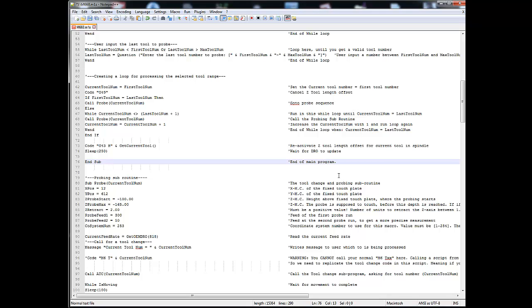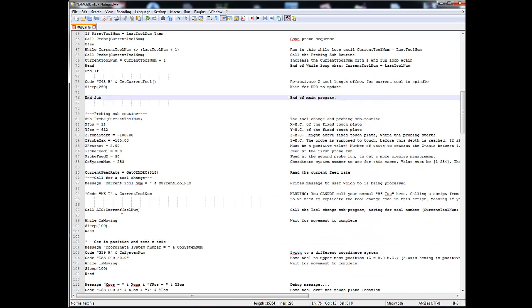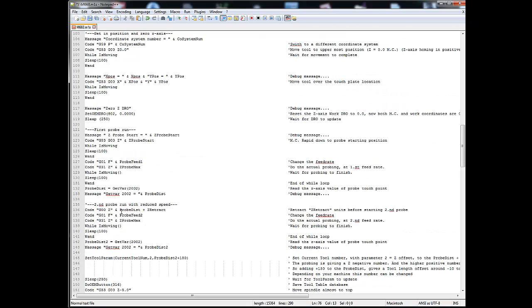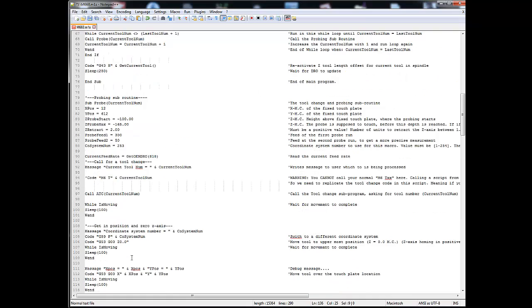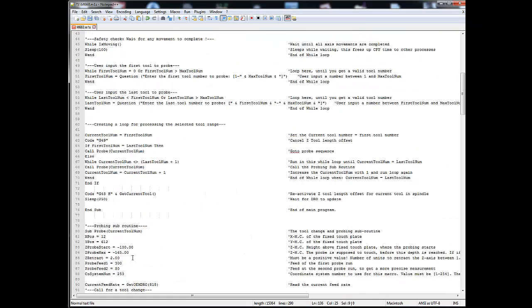What really bugged me and what took me quite a while to find out is that the distance in the probe is not compensated for with the tool length offset. So you'll need to deactivate the tool length offset. And another thing, the tool length offset is really the root of much evil in this. So if you can deactivate it as soon as possible.